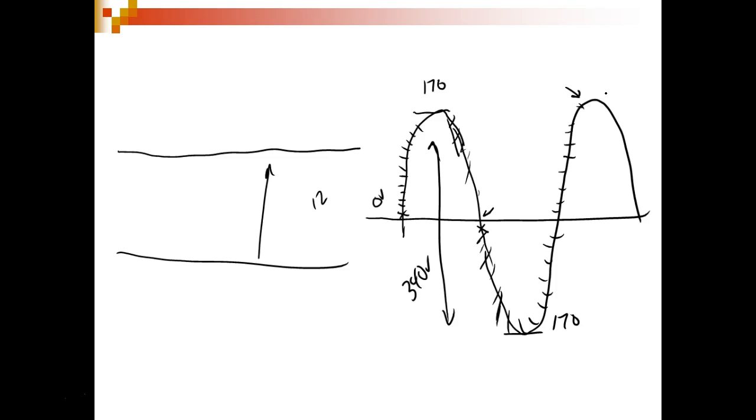So if they say 120 volts and it's AC, and they don't tell you it's peak, then it's RMS. Now, this is what we call a sine wave, which means it varies perfectly, so your positive and negative alternations are totally equal to each other.